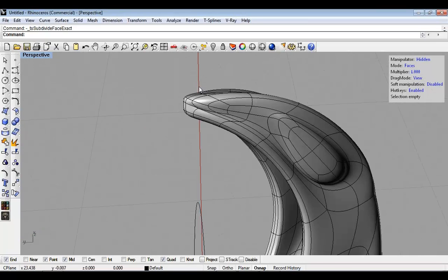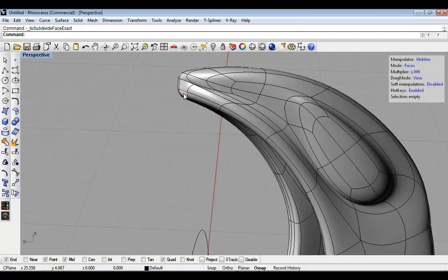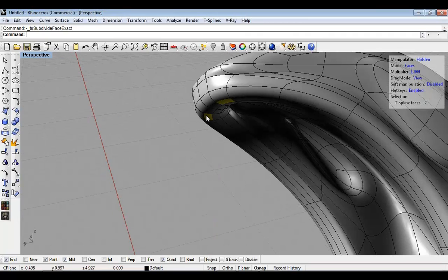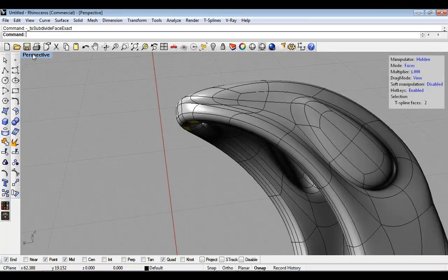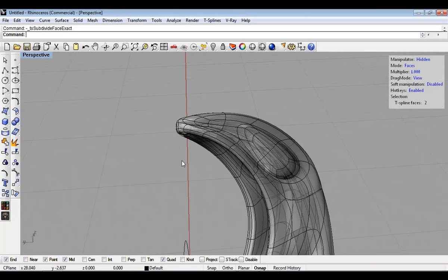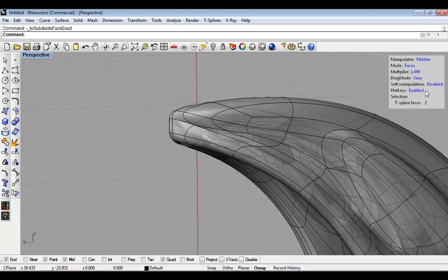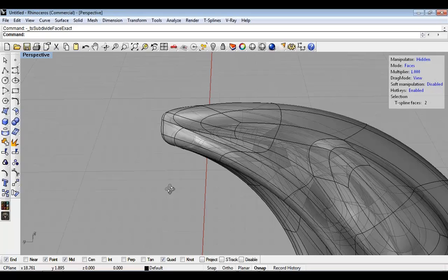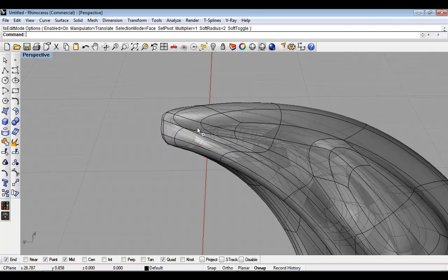And let's pull our teeth out. To pull the teeth out, I'm going to grab that and that. I'm going to go back to my ghosted mode now. What I'm doing here is using my drag mode in view, lining up the two yellow sections over each other so that I know that I'm more or less perpendicular. And I'm going to hold down the Alt key and drag these out, kind of like that. Now remembering, I don't want these to come out really far.